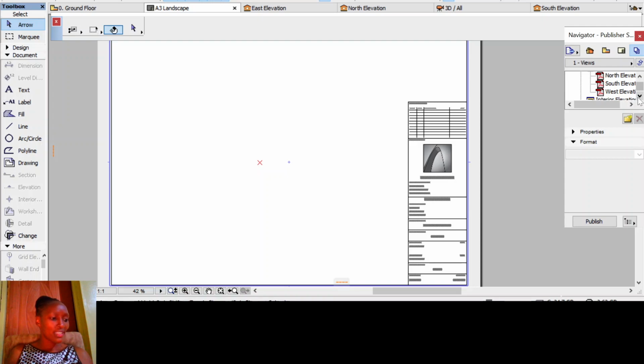The publisher sets map is a tree structure in which you define sets of views for various output purposes. If you want to print, you'll be able to save those different layouts from the publisher set. You go to printing, if you want to print, to plot, to save to a local hard disk, or to upload to the internet or the intranet, that is where you'll be able to do all that in the publisher sets.